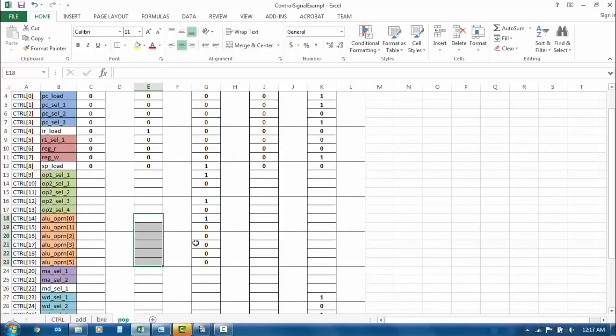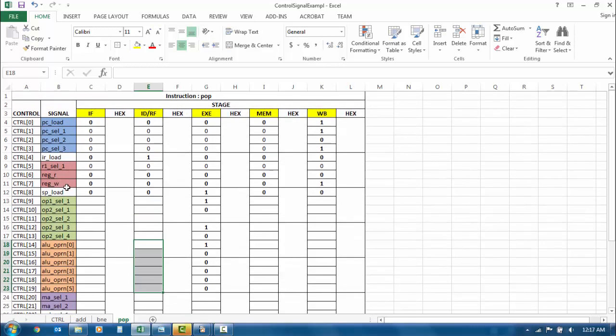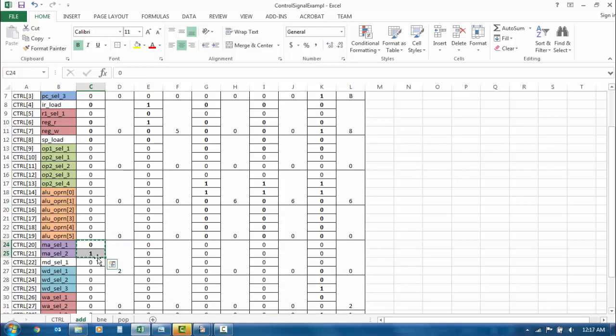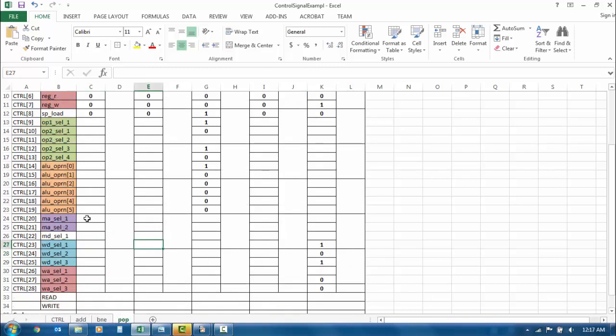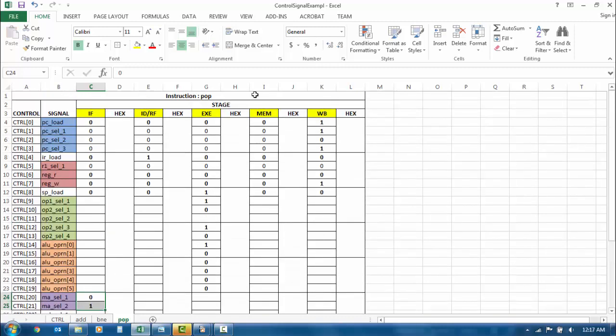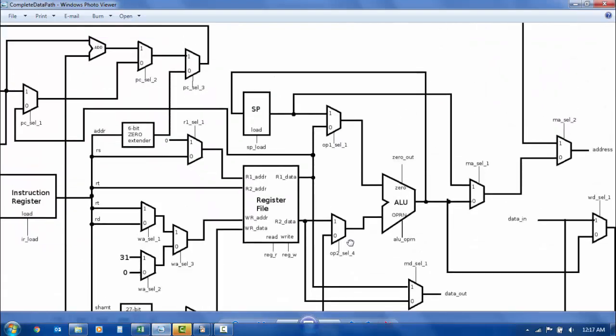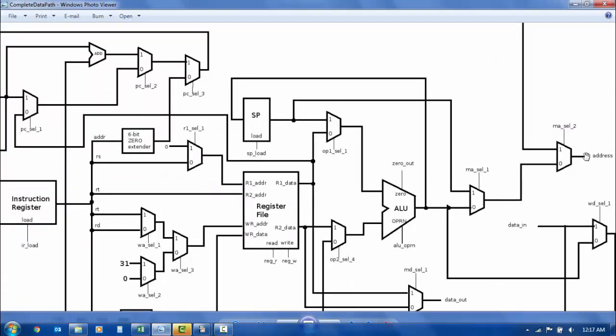Okay. Now memory address selection, let's talk about that. We took care of this whole thing, so we are done with practically this set. Now how about the memory address selection? Instruction fetch is the same as the AND, so this will be like this. And it is important during the memory access, where I need to send the stack pointer address as an address, right?